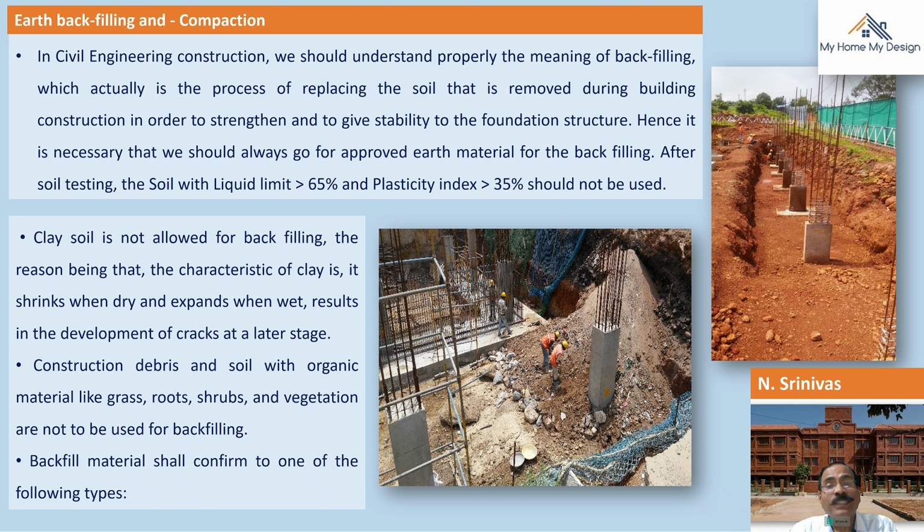Then what is the right way? For the backfilling material, we should always go for the approved backfilling earth material as per IS. That gives the indication that soil with liquid limit greater than 65% and plasticity index greater than 35% should not be used. It should be less than, within these limits. How do we know that? We need to go for the soil exploration test for such results. Okay, so this is the understanding of this paragraph.